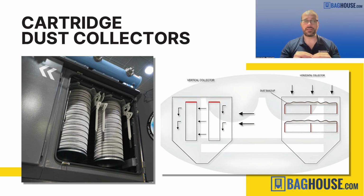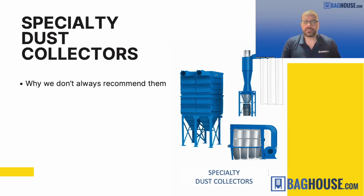You can use them on applications like that if you have a pre-filter like a cyclone to remove the big pieces. If you do that, then yes, you have no problem using a cartridge collector. And if you only have very fine sawdust, a cartridge collector can be a very economical option as well, granted that you size it conservatively, and again, avoid OEMs or resellers that try to tell you to jam a lot of air into a very small dust collector. Now, finally, there are some specialty dust collectors out there that get used for woodworking sometimes.